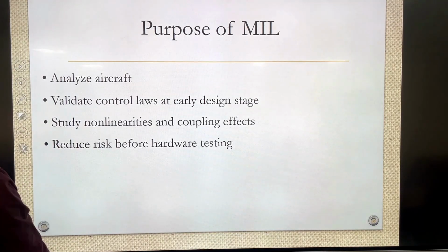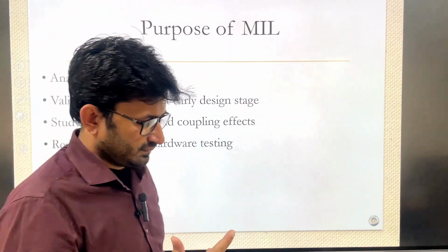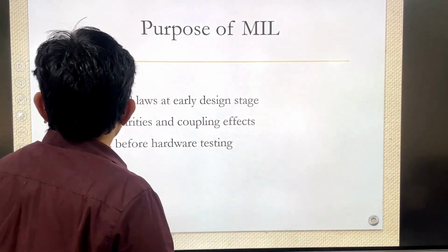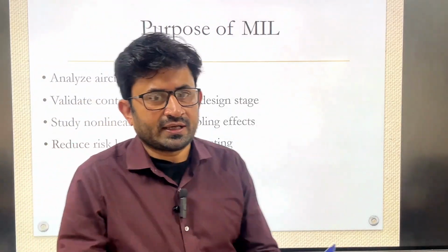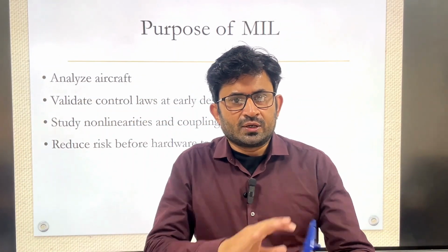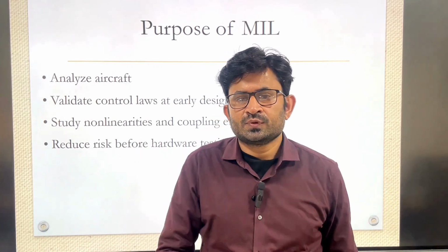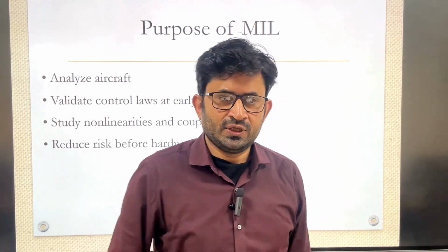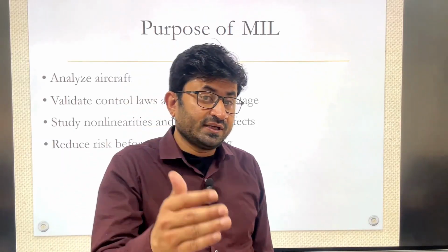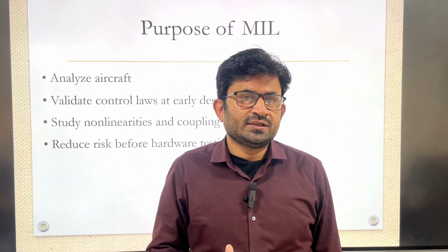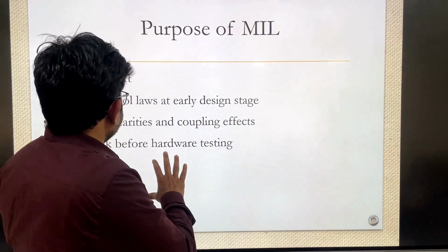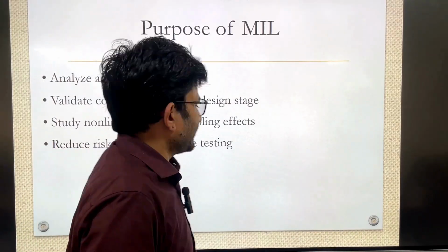All right. So what is the purpose of the model in loop simulation? See, if you are writing any code in MATLAB Simulink, you can analyze the aircraft. You can see how the aircraft is behaving naturally as well as during the forced response. And then validate the controller at the early design stage.